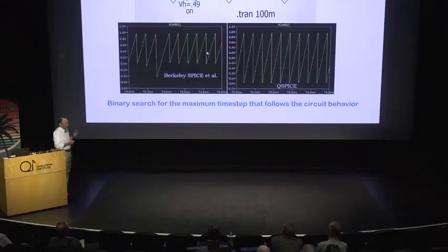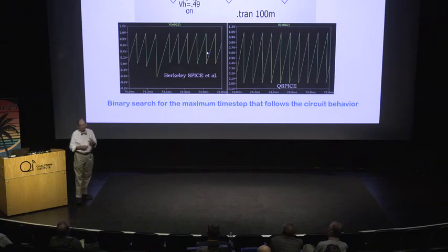And this is actually a desirable circuit to be able to simulate accurately because it only uses one node. And simulation time goes like the number of nodes and not the number of devices. So this is a desirable circuit, but Berkeley SPICE and LTspice confuse time step iteration with Newton iteration and can't give you the curve working right. Well, QSPICE just gets all that straight. It understands it. It works fine.